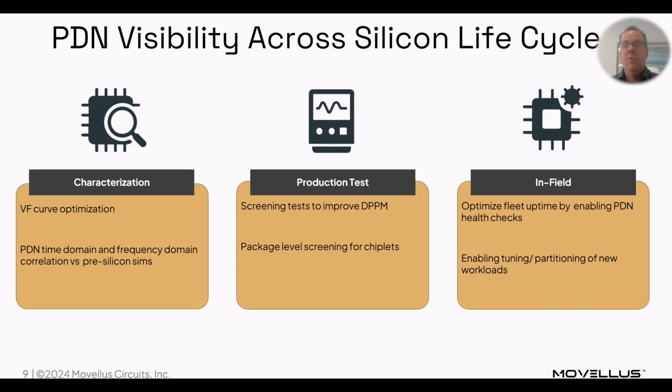This will be different from what you see in the field, because you will have a different, perhaps soldered versus socketed scenario, different decoupling environment. On the tester, you may have access to a lot larger decoupling capacitors on the test board, whereas in production in the field, you may have restrictions on component sizes or component counts or costs. And in between, you have production tests where you need to actually optimize so that you do not over or under margin. Again, over-margining, you might pass failing die because you have so much extra voltage, or you may fail good die because you have such a low voltage at the die, which is unrealistic relative to what it would see in the field.